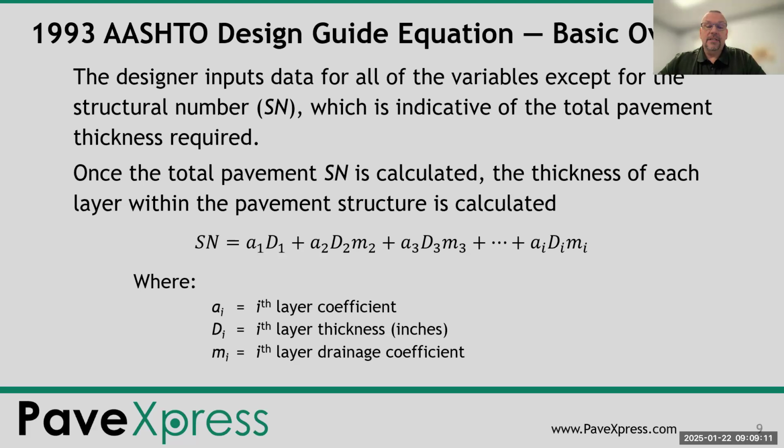So you can design your pavement and then calculate how much thickness you need there. There are different ways of doing it. You can do multiple layers of asphalt or just a single thickness of asphalt. The subbase is usually a set thickness, such as 6 or 8 inches of aggregate base. You can add in sand subbase layers. There are a lot of different options in there.